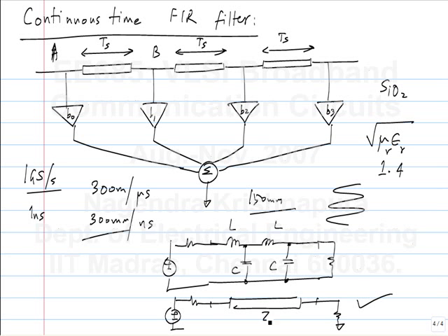So this is a transmission line of impedance Z0, terminated by R equal to Z0. What is the frequency response of this? Have you seen these things? What does it look like? I have a transmission line Z0 terminated with a resistance equal to Z0. What does it look like from here? It looks like a resistance Z0. So what is the frequency response of this? That is R, that also is Z0. Half. So it is flat. It is constant with frequency.